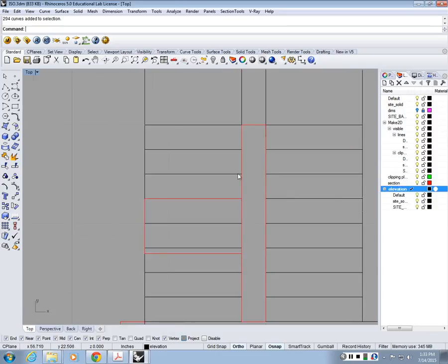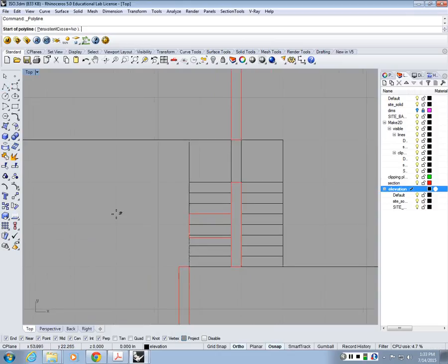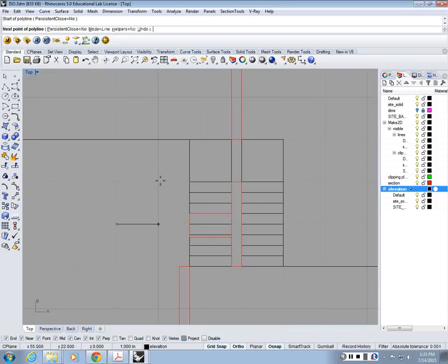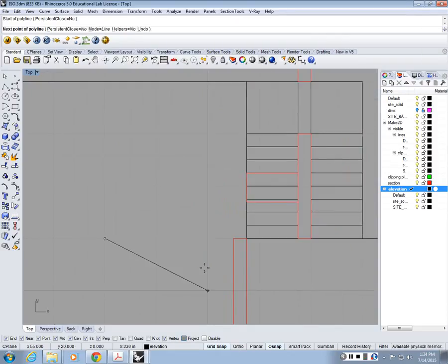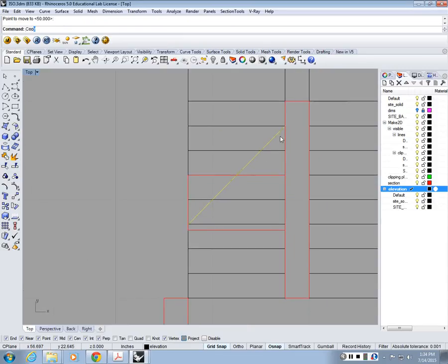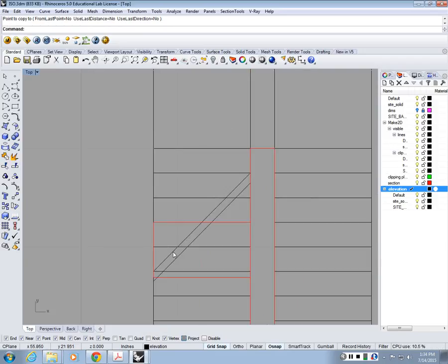So what I'm going to do instead is draw in this layer a 45-degree angle line, let me see if it will snap. Draw a 45-degree line like this, and then you want to place it somewhere here. And then make a copy. Let's move it by 0.1 inch, so you make it double lines. Now this is kind of the location where the stair is cut, right?